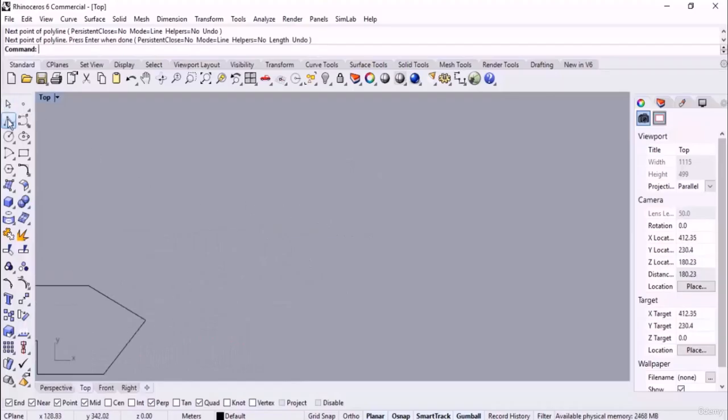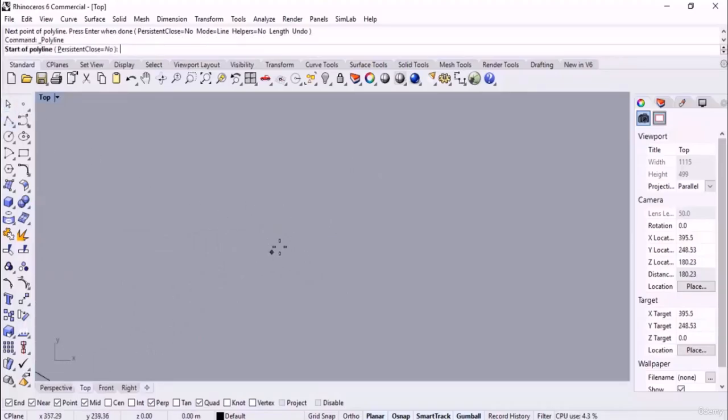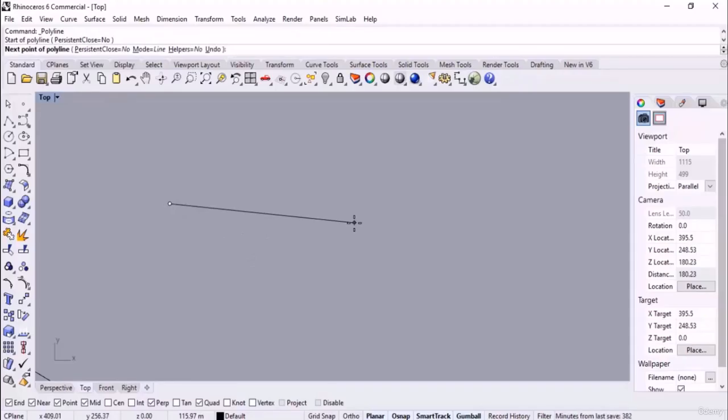Very well, but how can we sketch inclined lines or an angled line, and ortho should be inactive? However, if it was active, it didn't work out, but you'd better deactivate it. Anyway, in the process of sketching the angled lines, we got 3 stages. At the first stage, we should specify the angle. For example, I want an angled line in 30 degrees.